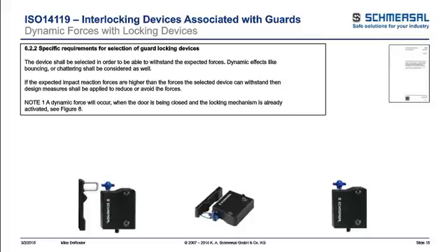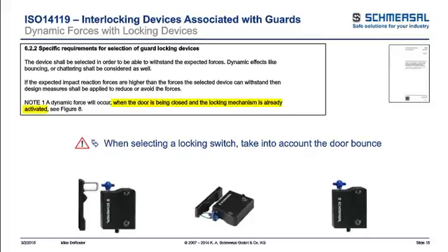Another consideration that a lot of times when you design your guards, something that's not taken into account is the dynamic forces associated with locking devices, especially when you're using an energize to unlock, or you initiate the lock command before the door is actually closed. Whenever you close the door, you have to look at what the dynamic forces are, and what the standard is meaning by that is looking at what the door is actually doing. Is there bounce in the door?